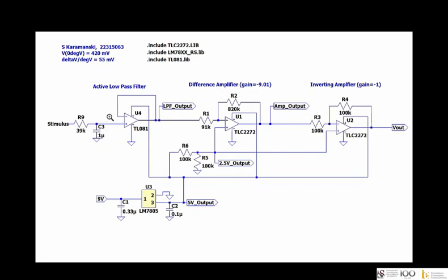So basically, we're using the op-amp buffers in order to create different blocks in our circuits, so that, for example, from this side, looking in here, we will see a very low impedance. And then looking in from this side, we'll see infinite impedance, so that this side of the circuit does not load this side.